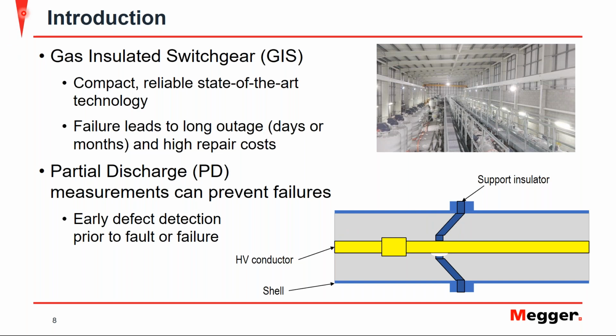Now, the gas is pressurized to increase the dielectric strength according to Paschen's law, which relates the breakdown voltage between two electrodes, in this case the ground potential and the high voltage potential, to pressure and the gap distance. Since the distance between the two is fixed, if you increase the pressure, you increase the overall breakdown voltage, therefore increasing the dielectric properties.